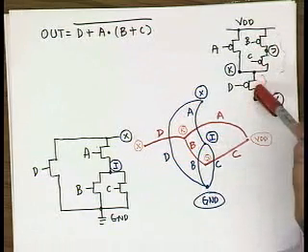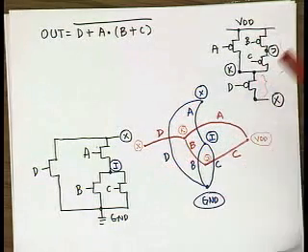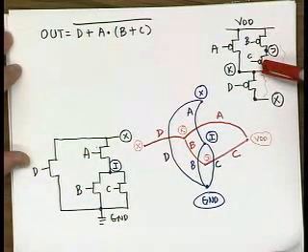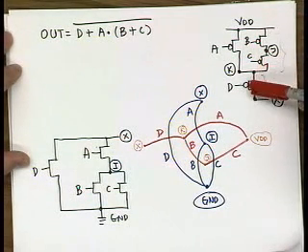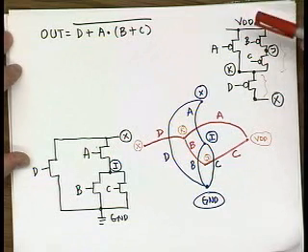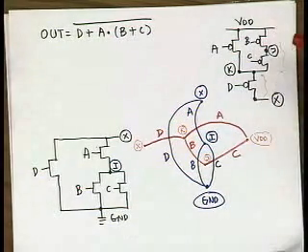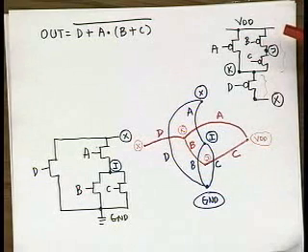So basically, there are a number of solutions for this pull-up and pull-down network as well. And you can certainly flip, for example, B and C over here, reverse the order, or you can put D on top, as you pointed out. And we will come to that later when we do delay analysis. We will see that rearranging and ordering of these signals really does influence the delay.